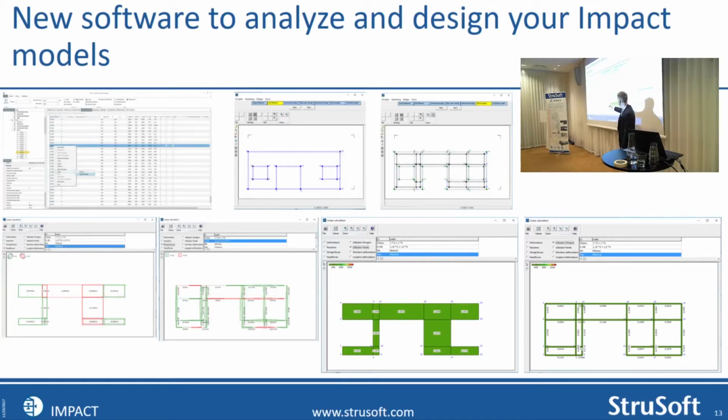And then the one you have here on the left is the shear force in the panels, in the hollow core panels. And of course, the joints in between the hollow core panels should be able to take this load. We have a check of that as well. So you have the panel forces, you have the reinforcement forces, the edge, the stringer forces here. And you have, of course, the Eurocode check of how much utilization you have of each hollow core shear field.